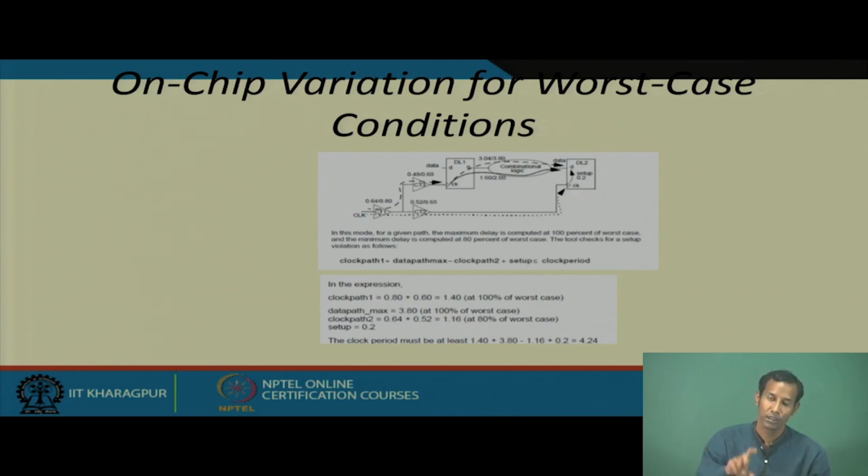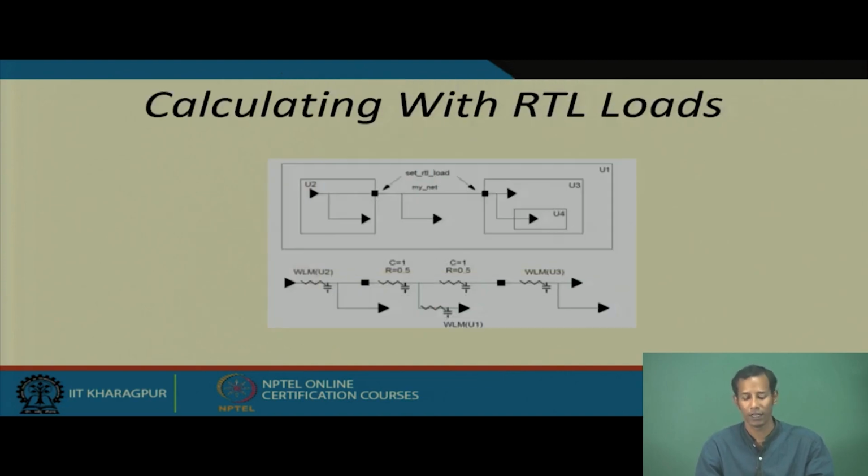Now, suppose from the circuit aspect you run that tool for timing analysis and then you see that for some paths you are getting some violation. At that time you can identify that path and then again calculate manually, this is the information about the delay. Now, what changes should I make so that I can overcome the problems of this violation and my chip works perfectly fine? So, for that reason you have to know what particular aspects you have to calculate for hold check as well as setup check while you are doing the timing analysis.